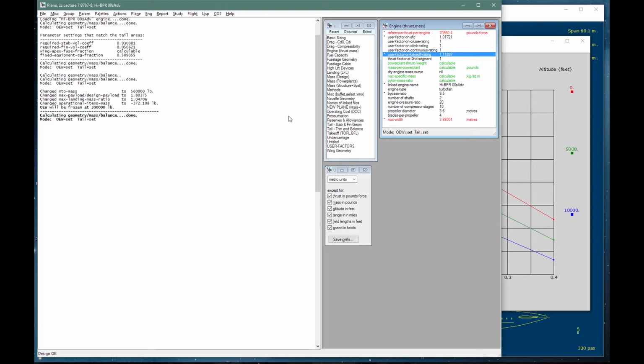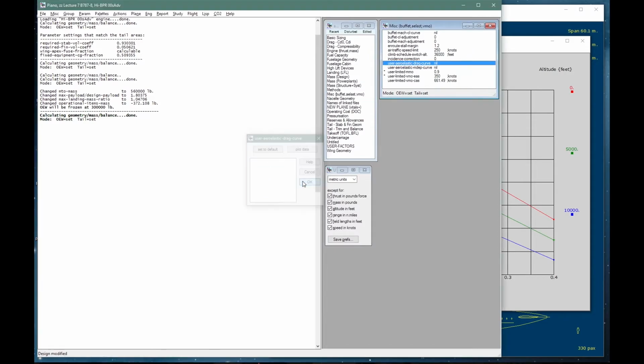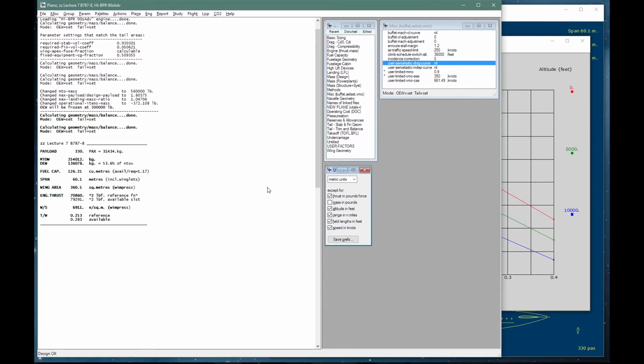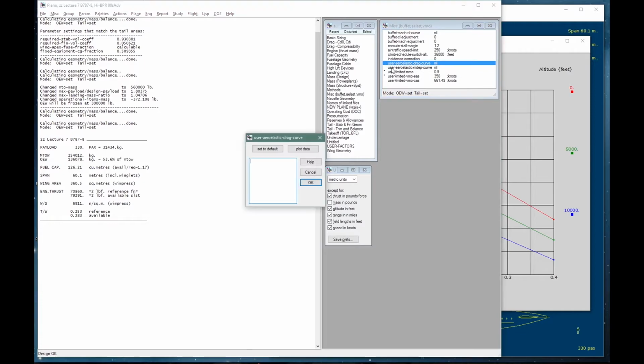What about aeroelasticity? Clearly we don't want to use the adjustments that we made for the Dash 8, as our weights are now very different. We clearly expect much more experience to be incorporated in the Dash 10 with structural modifications and/or software tweaks for the trailing edge variable camber and load alleviation systems. So I will apply no adjustment at the lowest weights, let's say roughly 135 tons, and just the 1% adjustment at the highest weight, let's say roughly 250 tons.